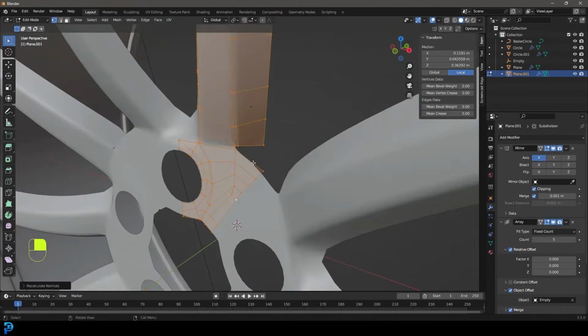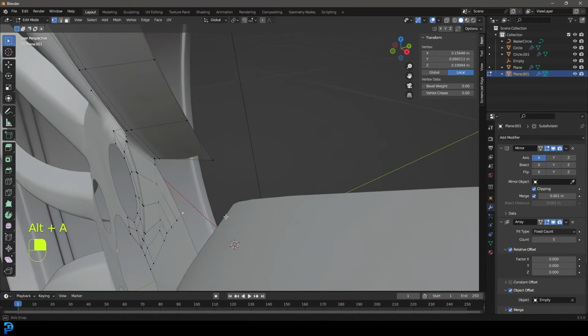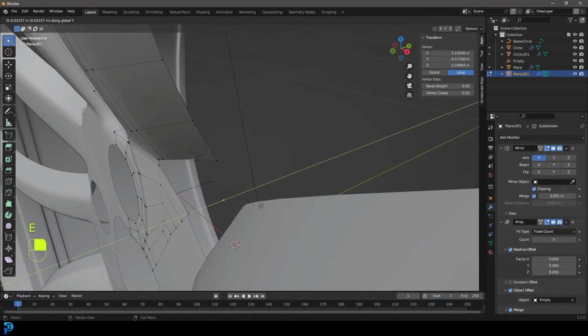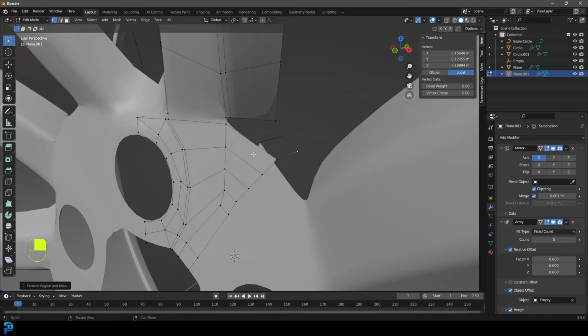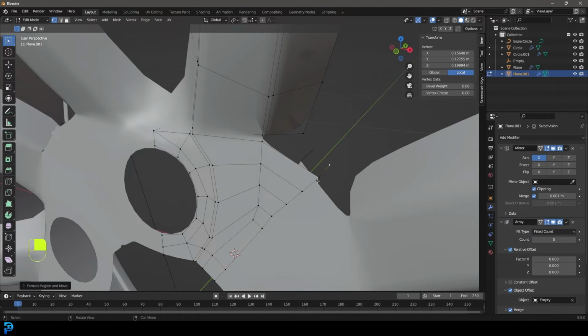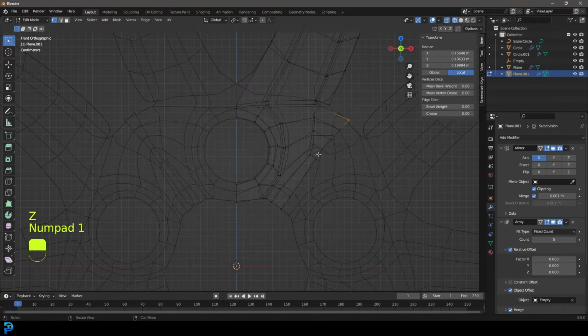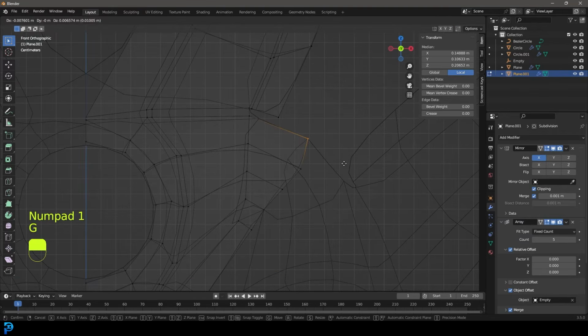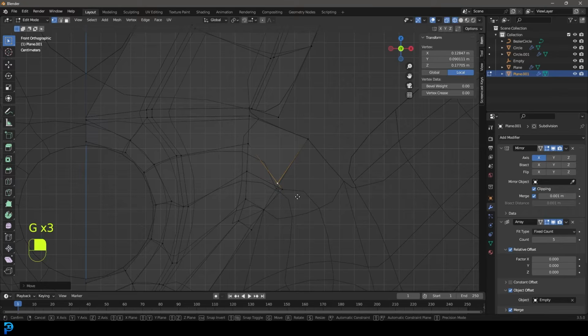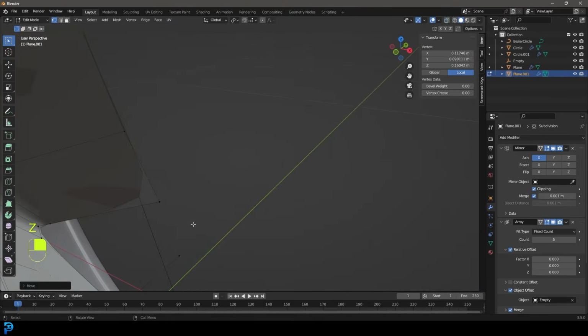So now in edit mode, let's grab this vertex here, go E to extrude and Y to move it back. And we can see with these ones here, they're kind of overlapping. So let's go into our front view and in wireframe, let's move them up like so, till they all kind of fuse. So bring these ones here and these ones here. Okay, there we go.